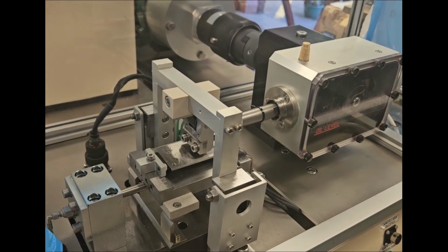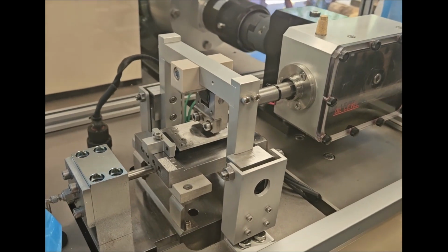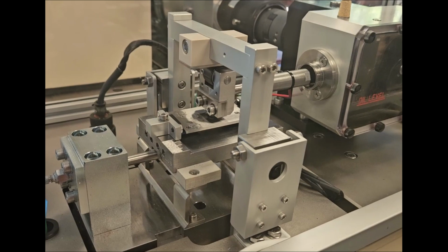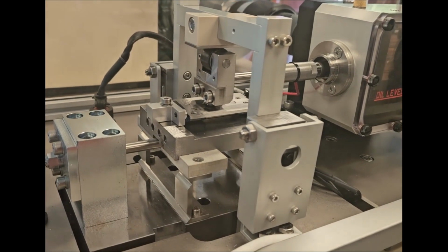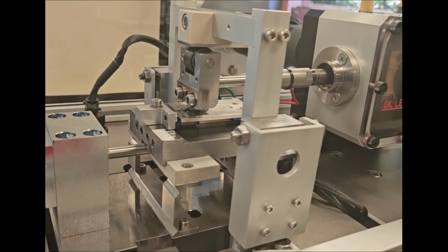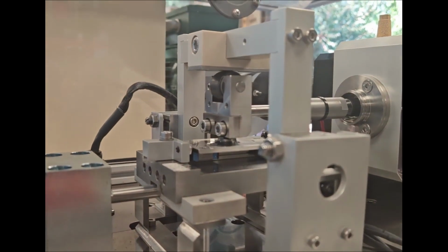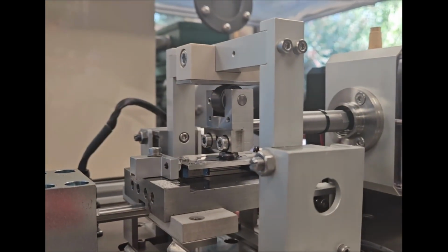An interesting feature of our test today is that the friction is dependent on the sliding direction. This is going to be something to do with our test specimens. Maybe there's a difference in surface roughness depending on the direction in which the components are being machined.